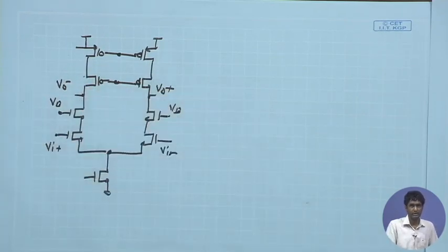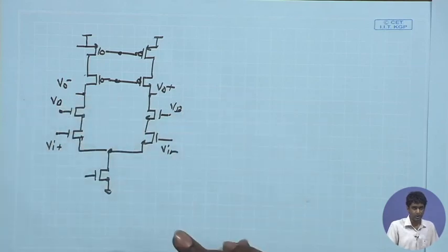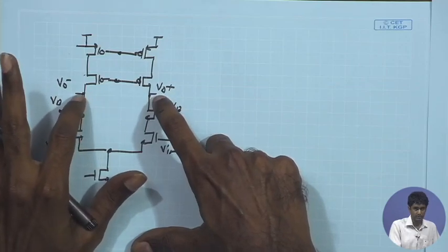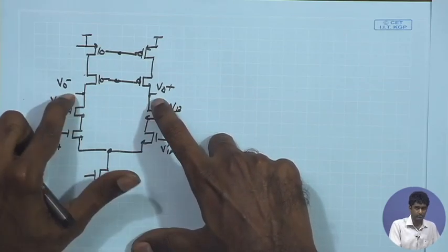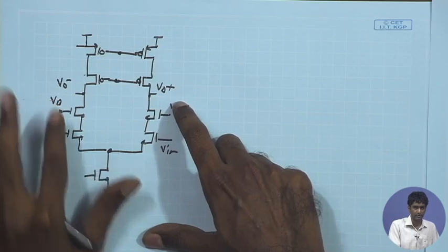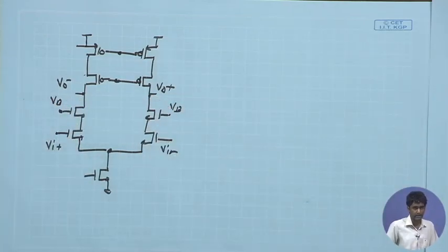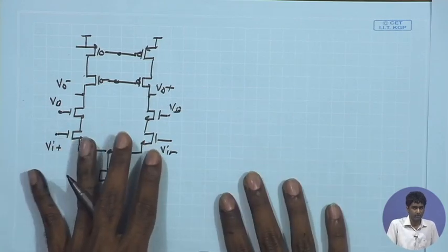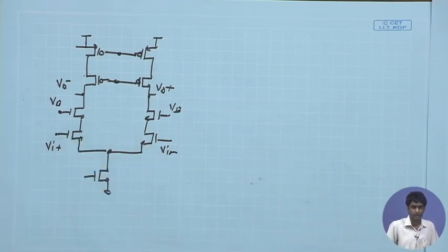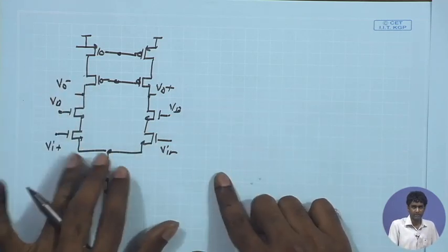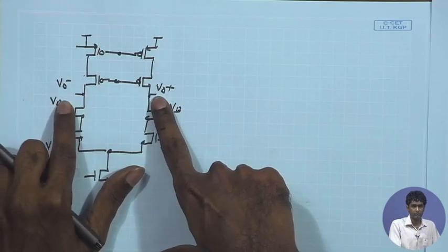and if I am using this particular circuit for closed loop operation, I would like to compensate the output node over here directly. Because this is a dominant pole, I would simply like to put some more capacitor over here so that the dominant pole gets shifted further towards lower frequency and I can get a better phase margin. So here we have the dominant pole compensation coming into picture. So here we are not going to rely on Miller capacitance, we are not going to use Miller compensation, but going for dominant pole compensation.